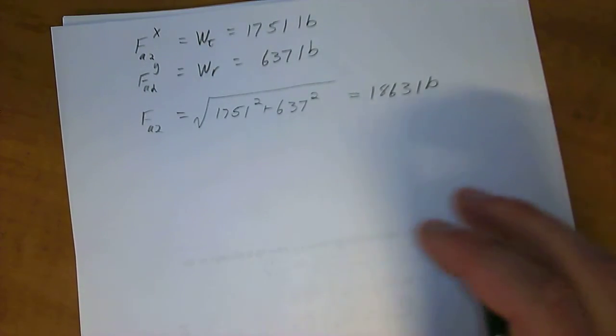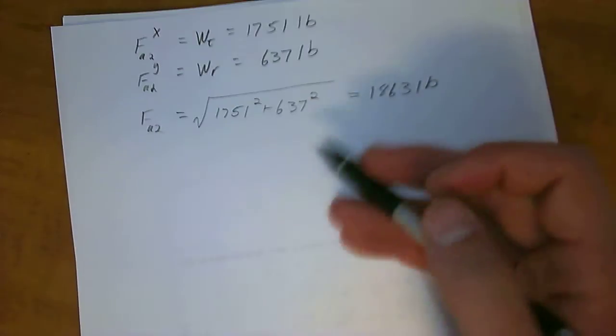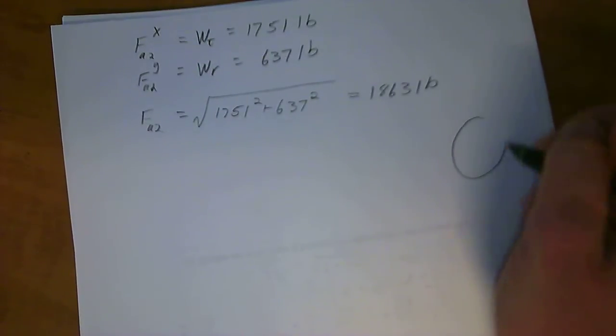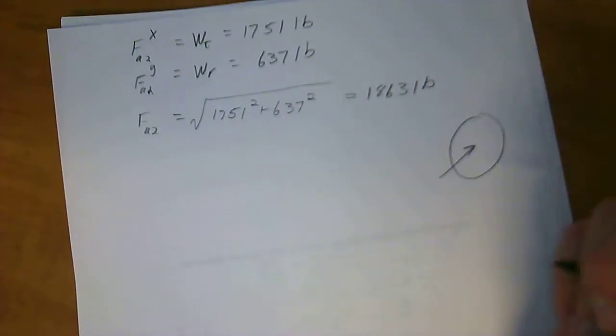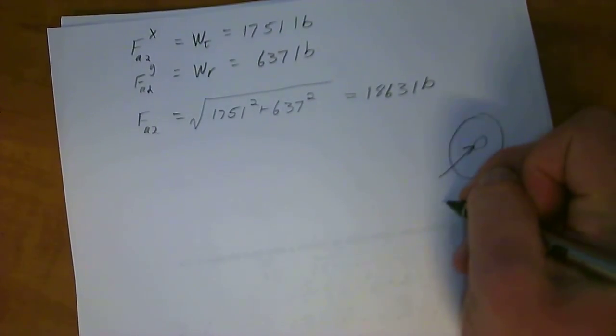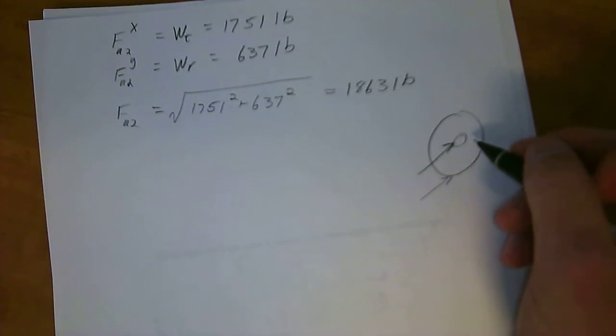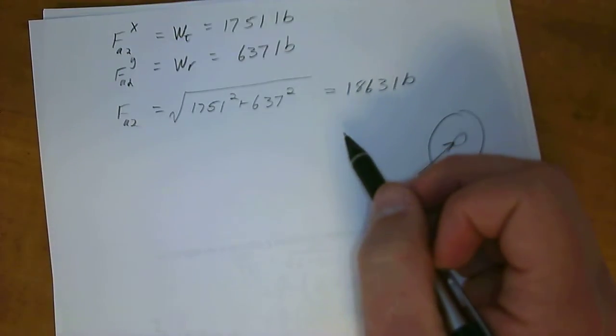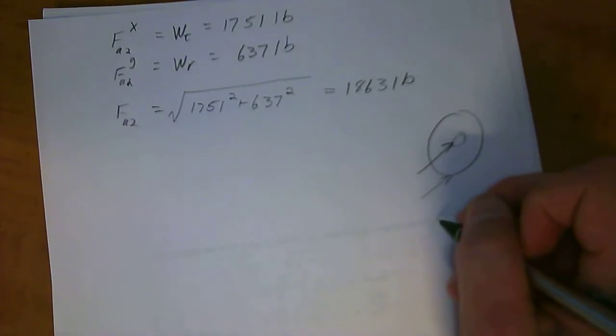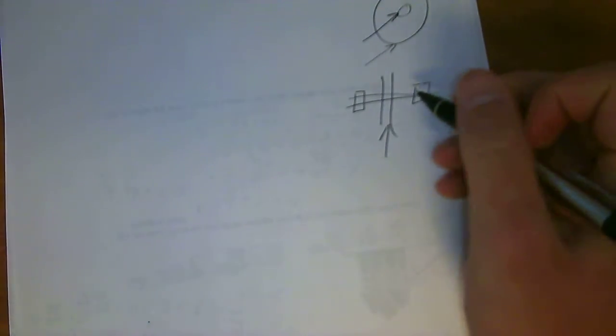Alrighty. So then we've got this force acting up on this gear, basically acting right there on the pinion, because it's acting down here. It's going to be acting through the pin or through the shaft as well. So then all you have to do really is say, okay, well, on our gear, we've got a bearing right here and a bearing right here. Both of them are equidistant from the gear, where this force is acting up on an angle, and since the gears are circular, it doesn't matter what angle this force is acting at, because it's going to act on these the same way.